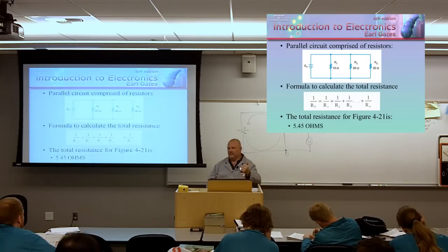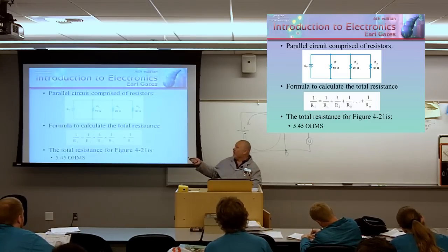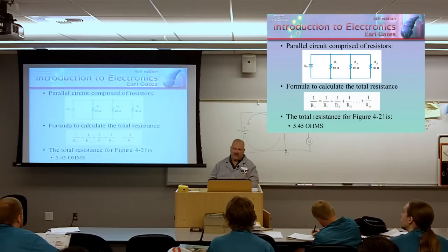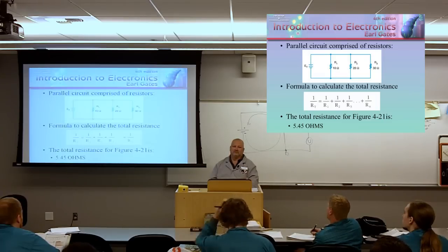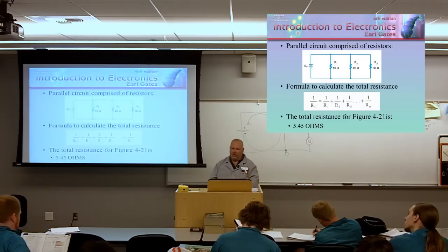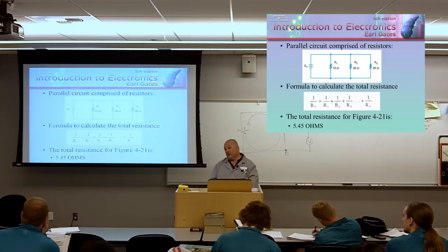That's a thumb rule. So if I've got 4 100 ohm resistors in parallel, 100 ohms divided by 4 equals 25. If I have 2 50 ohm resistors in parallel with each other, 50 divided by 2, 25. So that's a thumb rule, only if the values are equal.